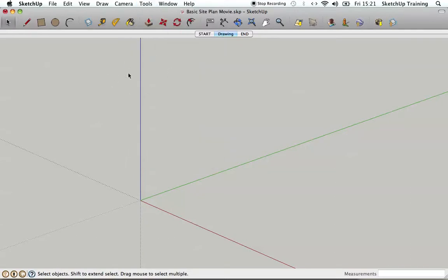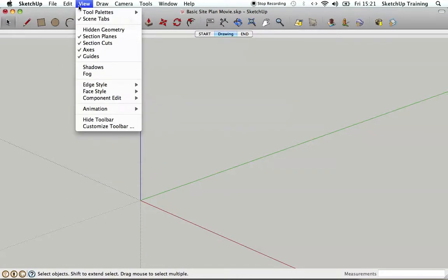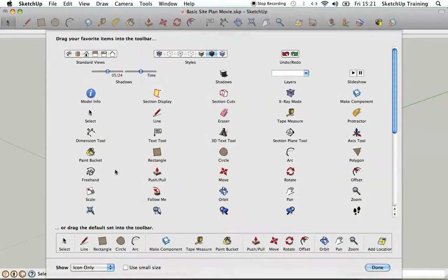We also use the full tools palette, if you remember, which takes a rather lot of space. So if there are tools we know we're going to be using a lot, or specifically for a short period of time but quite frequently, a way to adapt is to customize your toolbar. So if we go to view, and we customize the toolbar, we come up with a palette here. Now what we want to do is add two tools, the text and the dimension tool. I've already got them added, so I'm just going to go through the process to show you. I'm going to get that text tool and put it up there, and that's there. Now if I want to get rid of it, I could drag it back and drop it in there, and it's gone.